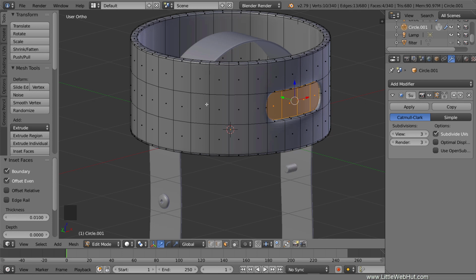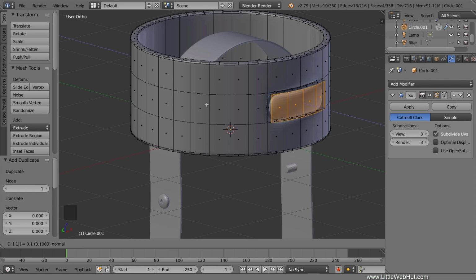This will give us 2 separate meshes, one for the ring and one for the button. This will make it easier to add separate materials to them later. To duplicate the faces without moving them, press Shift-D and then right-click. These new faces are the back of the button. To add thickness to it, extrude by pressing E, then 0.1, then Enter.